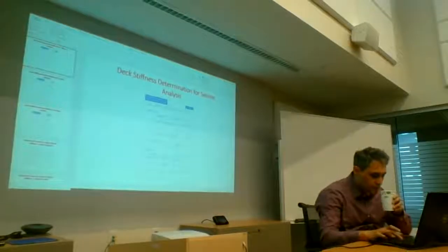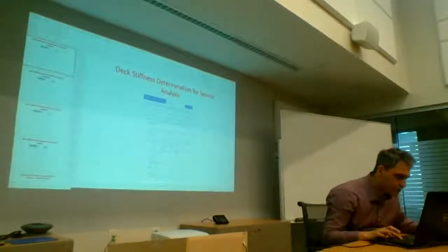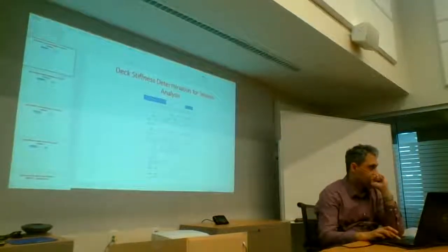That's right. If in Revit you only do the architectural model and then export that to SAP, then this is definitely the trouble you're getting in. But if you first create a structural model in Revit and then export it, it will be as it is, 100%. Even with the loads, you can apply loads even in Revit and then they will be exported.